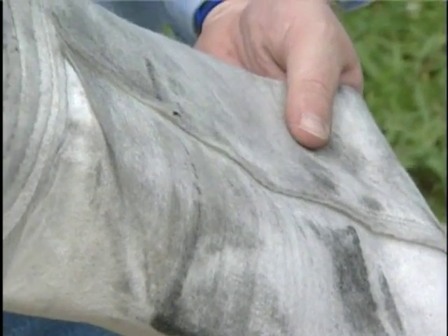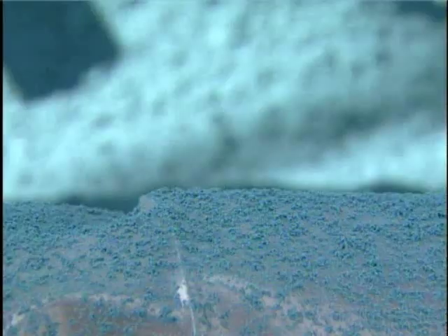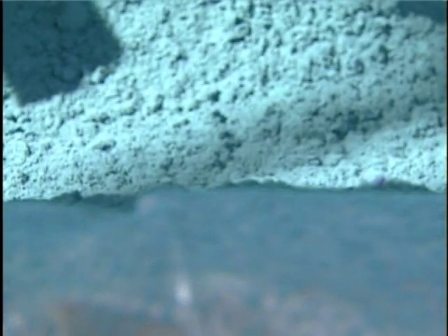The fabric used in pulse jet collectors is usually a heavyweight felted fiber material. The fiber that is used is again chosen based on the characteristics of the particles and the gas stream, and on its ability to withstand the forces of cleaning.